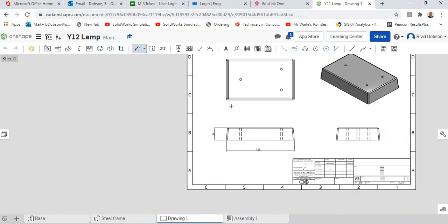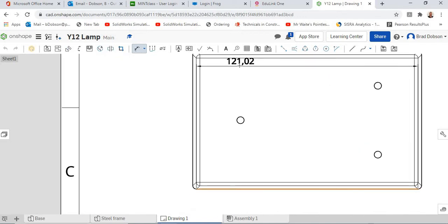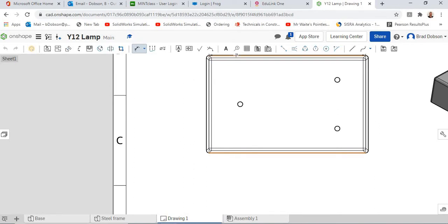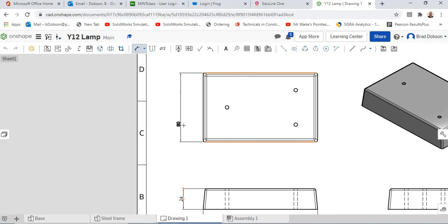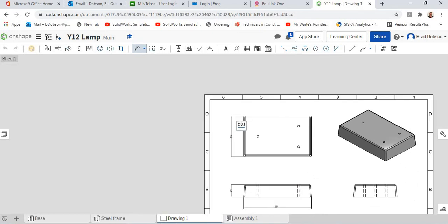Don't worry about that. I'm then going to put the width on. So again, I'm going to select that side. Just zoom in a little bit. Select that top line. It'll allow me to dimension that. Again, if I get close, you'll see that it's doing this sort of inference bit, so it wants me to try and line it up. Again, it's always good practice on a working drawing to get everything nicely in line. So that can be added on.